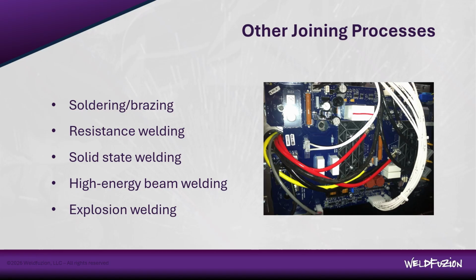There's even a process known as explosion welding, among others, which is typically used for cladding a thin layer of highly alloyed material, right? The pricey stuff, the unobtainium, the expensive material you have to buy for corrosion resistance or whatever property, over a more economical shell, right? Something like low carbon steel that's easy to form, a little bit less expensive, and with that lined, very, very thin liner of material, you can really make some economical parts that way.